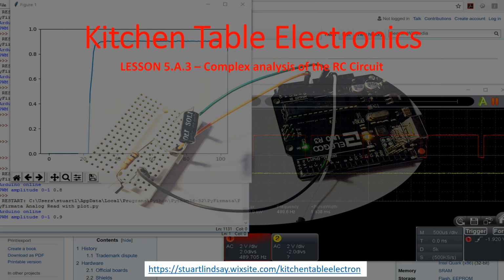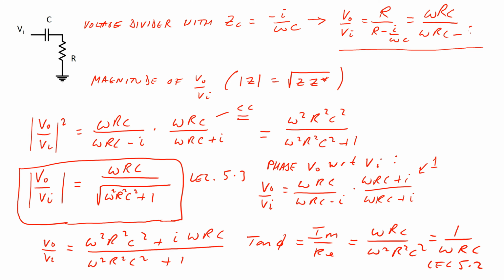Kitchen Table Electronics, Advanced Topics for Lesson 5, Number 3, Complex Analysis of the RC Circuit. Okay, so let's go back to our high-pass filter with a capacitor in series with a resistor, and we measure the output voltage here. This is the input voltage here, and once again we're assuming they're sine waves so we can use our newly learned complex analysis.